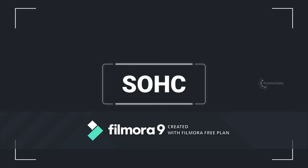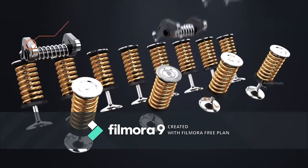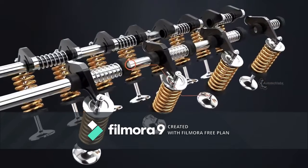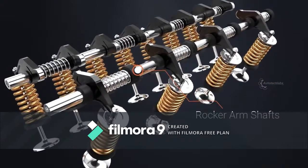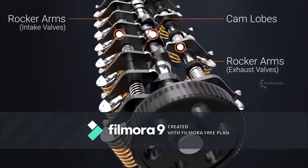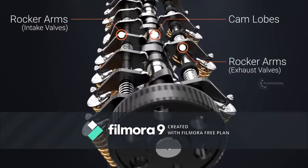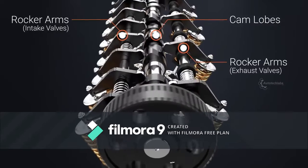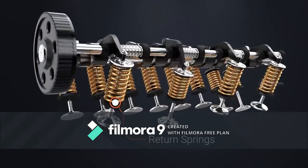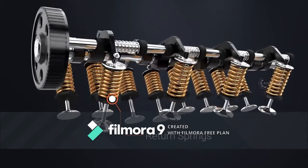Let's have a look at the SOHC configuration. An SOHC engine head is packed with intake and exhaust valves, rocker arms, rocker arm shafts, and a single camshaft. The camshaft is designed in such a manner that the cam lobes push the rocker arms at corresponding timings to open the valves. The return springs ensure that the valves lift back afterwards and keep tension on the lobes.